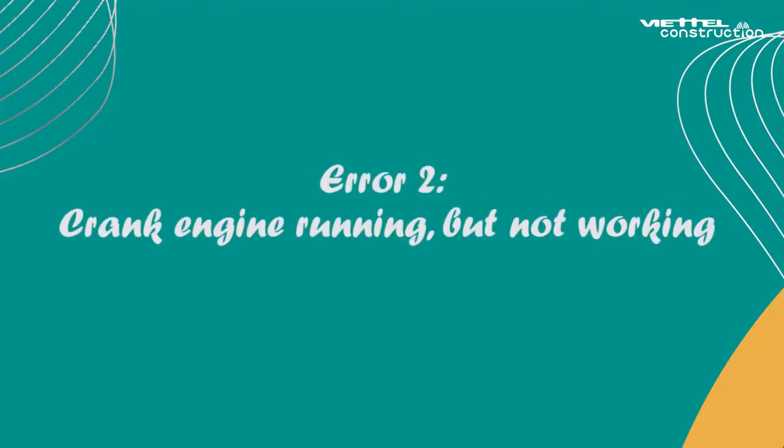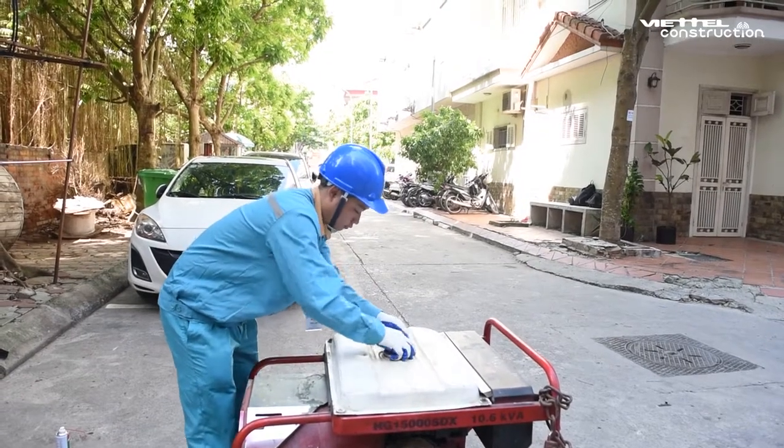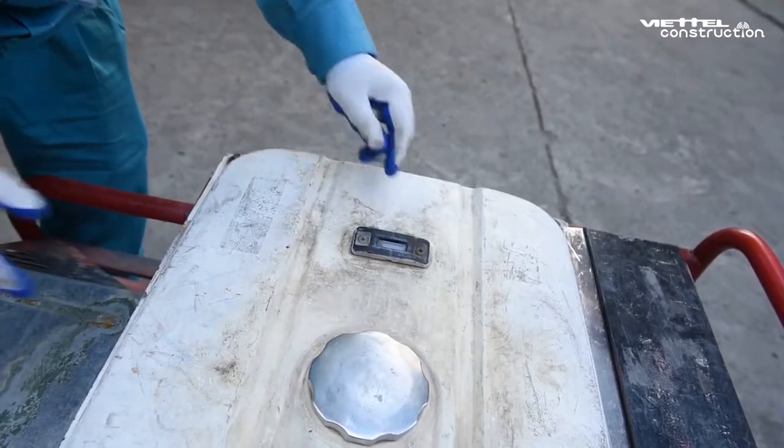Error 2. Crank engine running, but not working. Check the amount of fuel in the tank. If running out of fuel, fill it up.